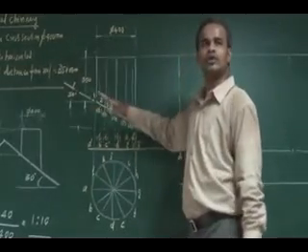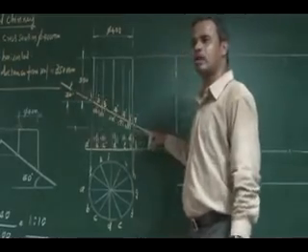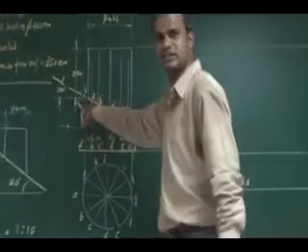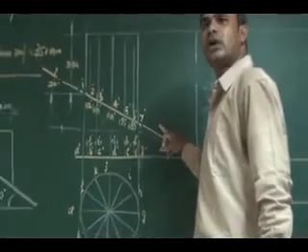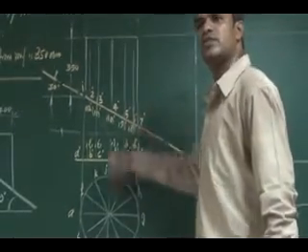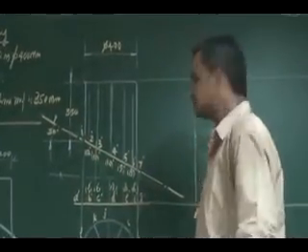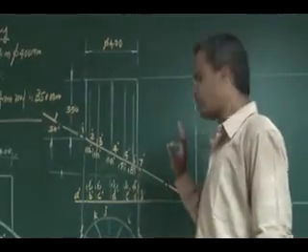So once I have shown that cutting plane as well, it will give me 12 cutting points such that it cuts all the 12 generators. So I am getting 12 cutting points. Okay, in a sequence you mark the cutting points, visible cutting points for the visible generators and hidden cutting points for the hidden generators. As usual, like your section of solids, you can represent 12 cutting points.